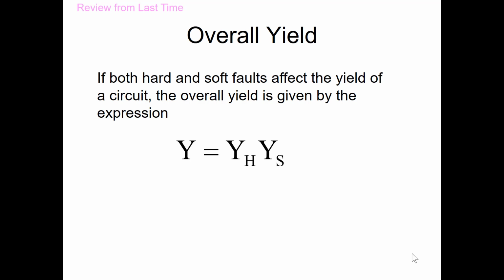Could happen in digital circuits too. Could be that the speed of a particular processor is not quite as fast as another one on the same die due to random variations in characteristics of devices. The one that operates faster is probably worth more than the one that operates slower. And indeed, a lot of times they will sell those faster parts as premium parts, or those slower parts, they'll discount the price on those. They come off on the same wafer at wafer sort.